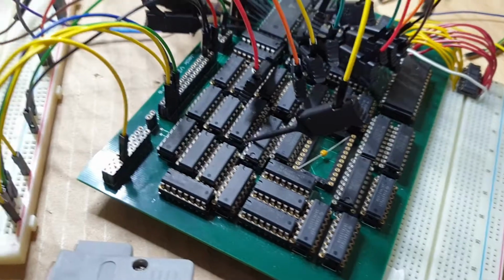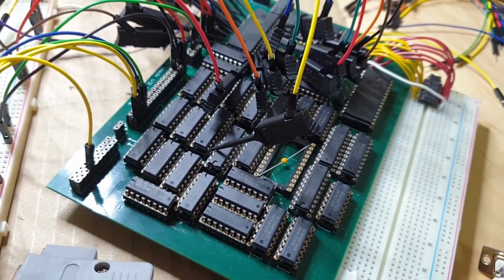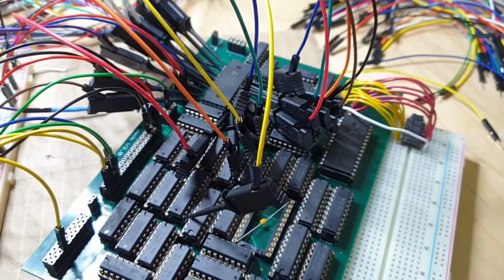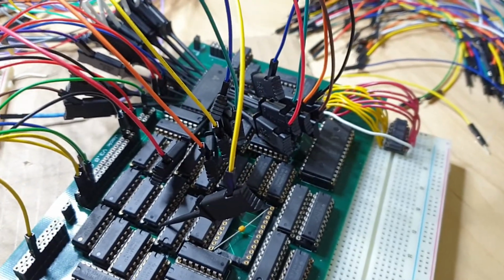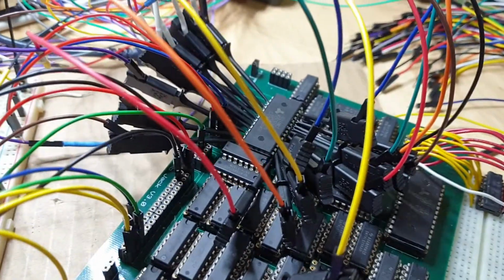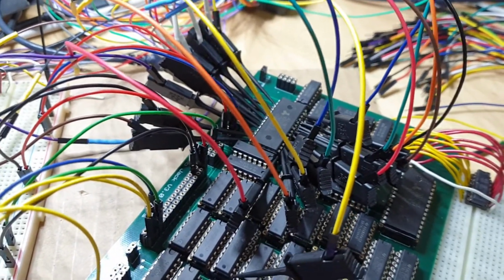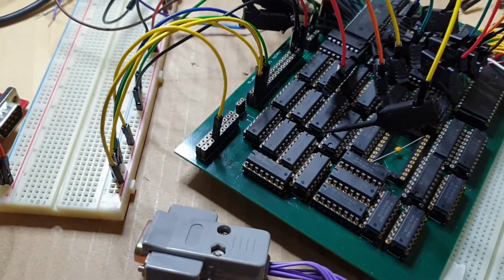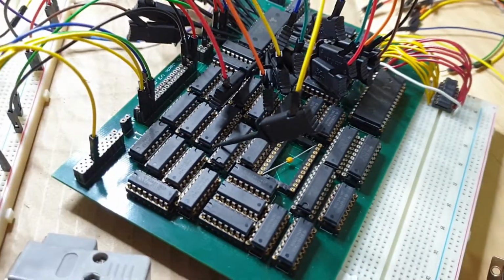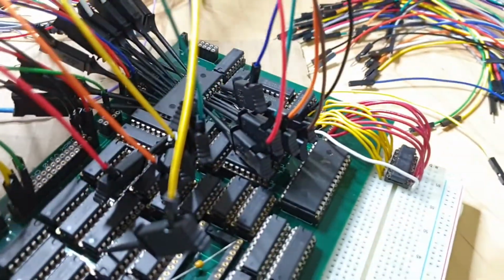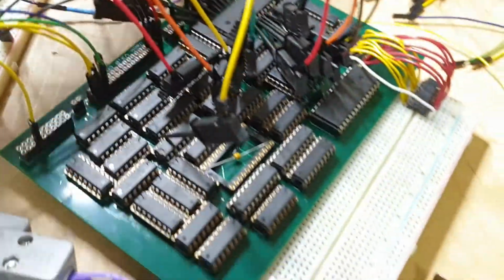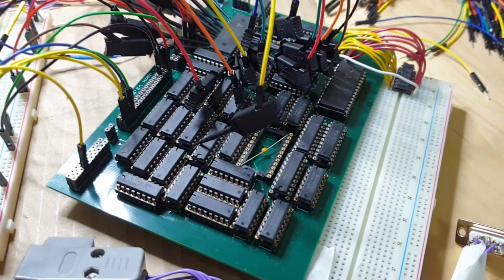This also here was testing the SL1 input as well, so just making sure that the logic, which takes the horizontal and vertical pixel positions and then generates the relevant load signals, was actually happening. So I had to basically fake a couple of coordinates here for the horizontal and vertical pixel positional values, if you like. And then down here as well, this is underscore CMP BLK, if I remember correctly. These ones were all set up by referring to all of this debug information here for the headers. So far the board seems to be behaving correctly.